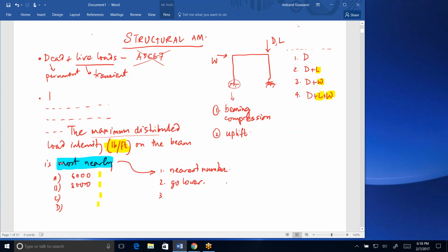An example of that might be, for example, in a wastewater treatment plant, they say that filters are designed for an optimum loading of 100 gallons per day per square foot or something like that. And then you figure out what is the area of filters required, and from that you figure out that you need 6.3 filters. But you can't use 6.3 filters, your choices are 6 or 7. In that case, you would have to go higher to 7 filters, because if you go down to 6, even though it's closer to your 6.3, the load on the filter will be exceeded above the critical value, right? So in that case, you can go higher to the next integer value.